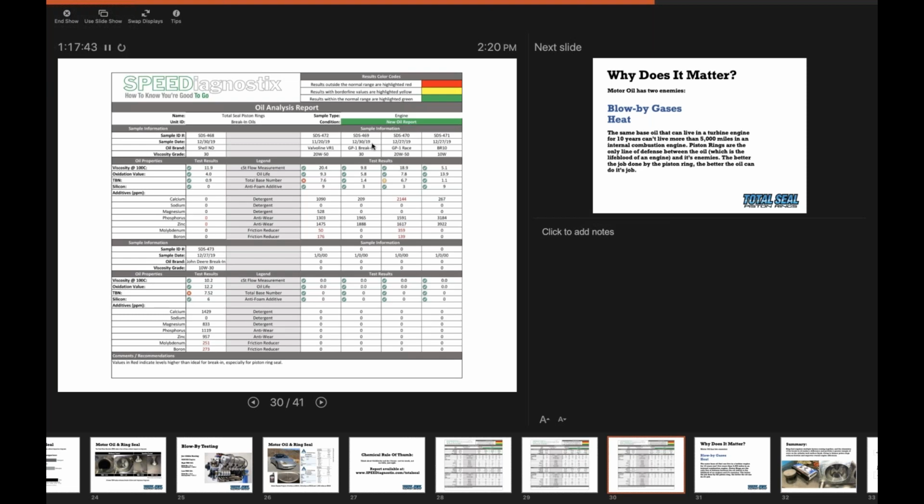Now, for the performance engines, like the competition engines, that's where we really recommend going with the stainless steel AP steel rings. So that's 440B stainless steel, and those work really, really good, up to about 1,500 horsepower. And again, all the benefits of gas porting, but those benefits last longer, less bore wear, more even bore wear, and you can do that with the 440B stainless.